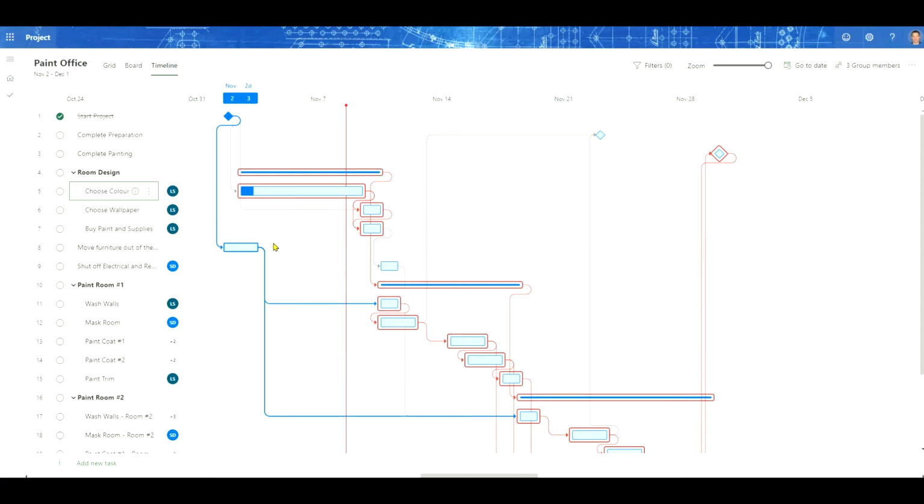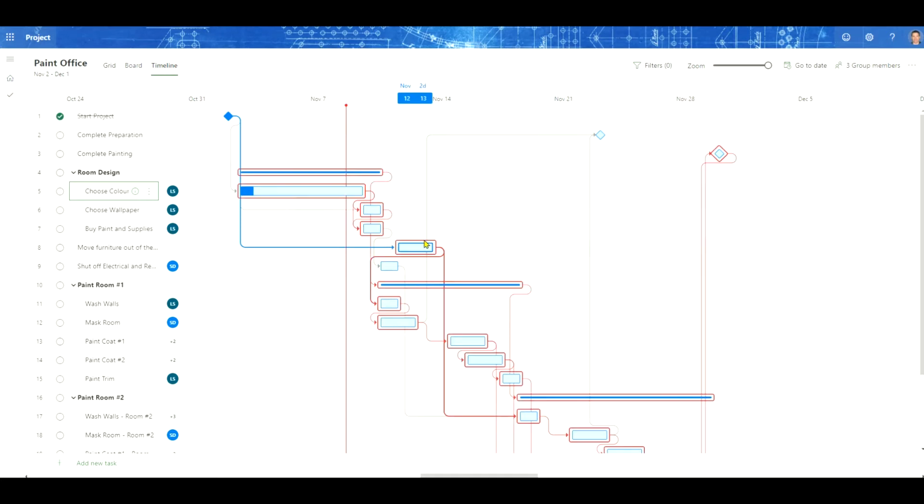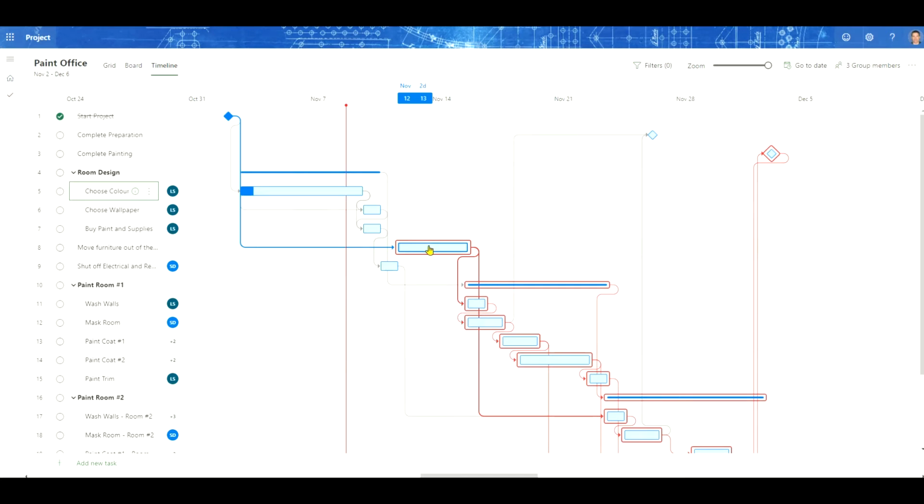Now we can see that we still have a task left behind here. This is all linked in like it's supposed to be, so mechanically inside the schedule it's well built. However, it's not on the critical path, so it hasn't been pushed forward. With this task, it's 0% complete, and what we want to do is instead of stretching it out, we want to move it. So what we do is hover over the task until we get the little finger, click and drag it across the November 9th date, and then release it. You can see in doing this, it's actually entered the critical path. If I were to pull it out further, it would become the critical path. Let's back it up and undo with Ctrl-Z.